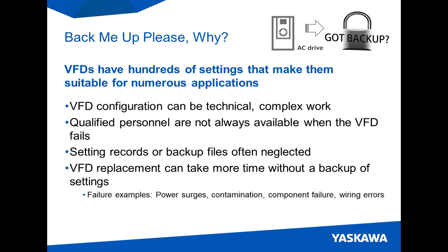So VFDs do have a service life. It could be 10 to 20 years or even more. Large VFDs can be quite expensive compared to the smaller VFDs, and so the more life we can squeeze out of those, the more it pays for itself many times over. So replacing circuit boards may require reprogramming. Having a setting record, or even better yet, having a backup file that can be quickly restored is a recommended practice.